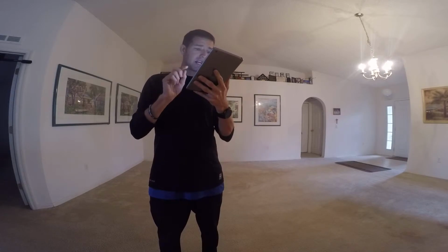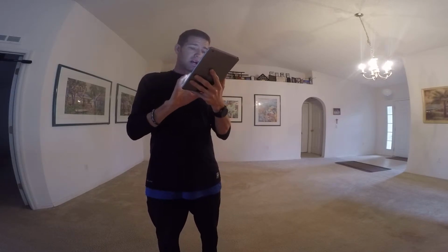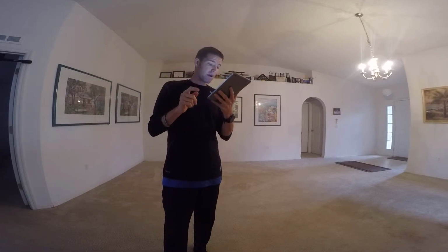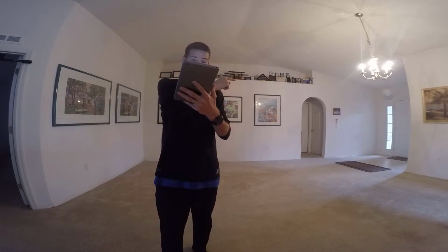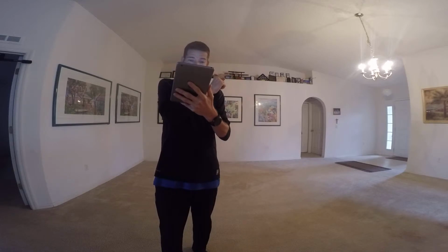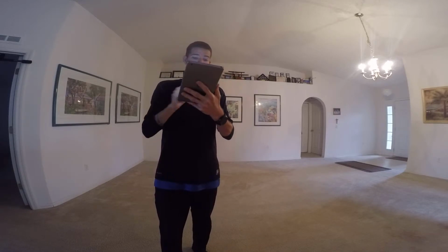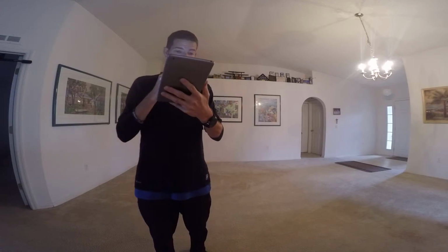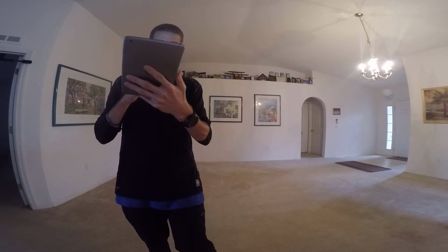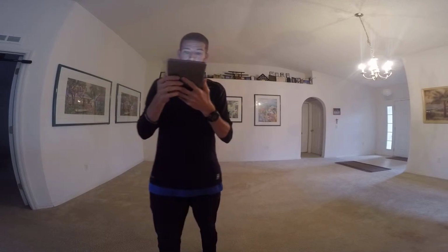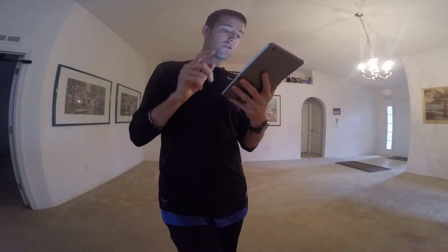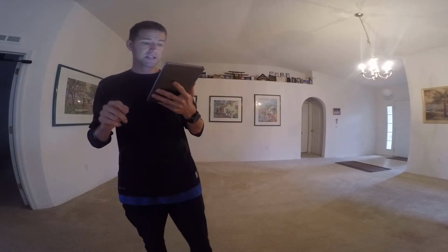Retreating blade. As relative wind speed of the retreating blade decreases, the blade loses lift and begins to flap down. It reaches its maximum downward velocity at the 9 o'clock position, where wind velocity is the least. This downward flap creates an upward flow of air and has the same effect as decreasing the induced flow velocity by imposing an upward vertical velocity vector to relative wind, which increases angle of attack.